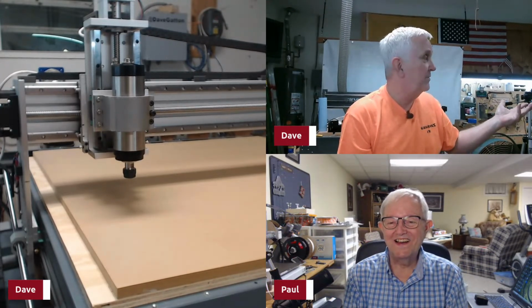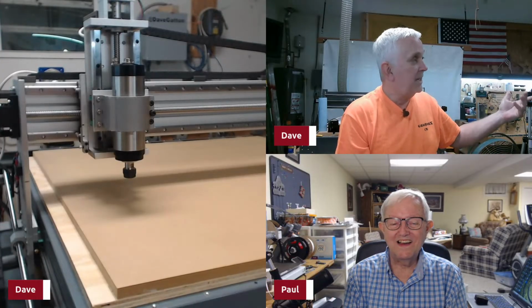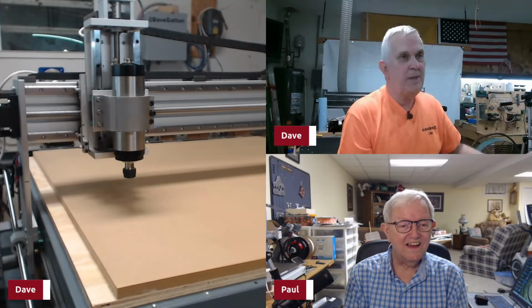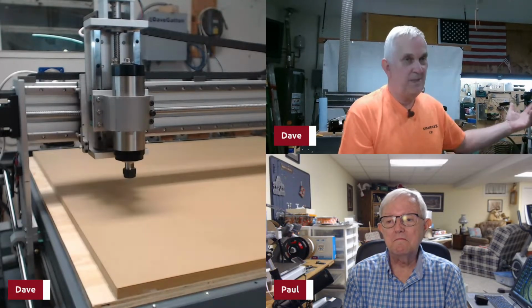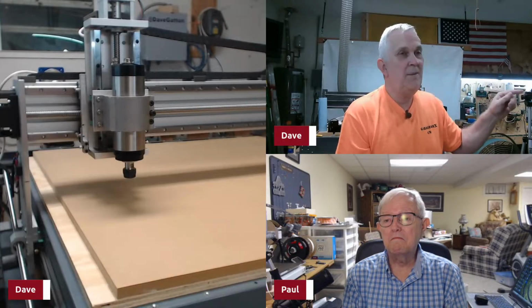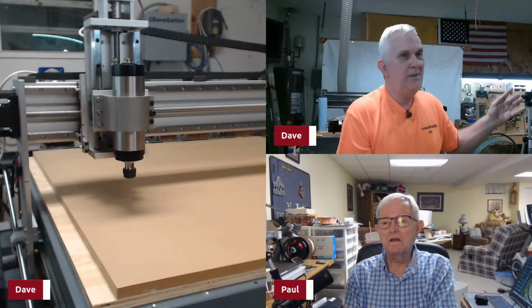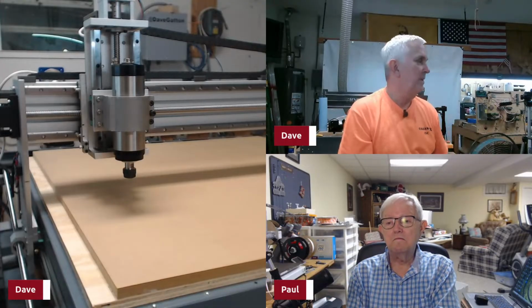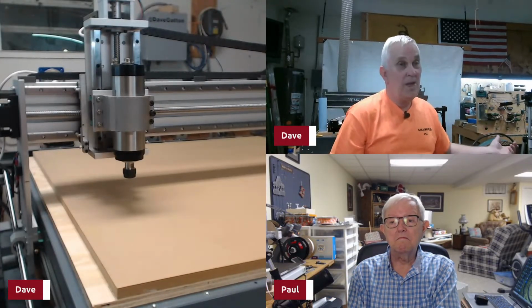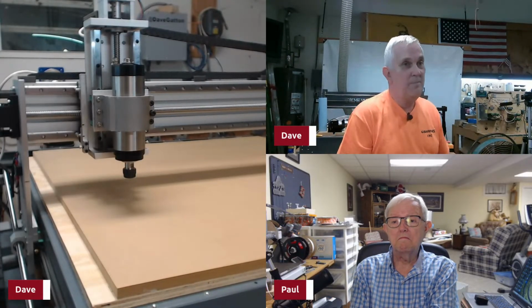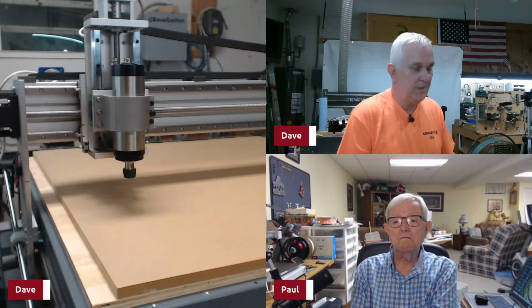I've really got conservative settings on all the X and the Y. I think I've got the max speed set at 300 inches a minute. But when I first set it up, I go, well, let's just see what it is. I put 500 inches a minute, and it'll do it no problem. And that's with not having the power turned up on those dip switches on the drivers.